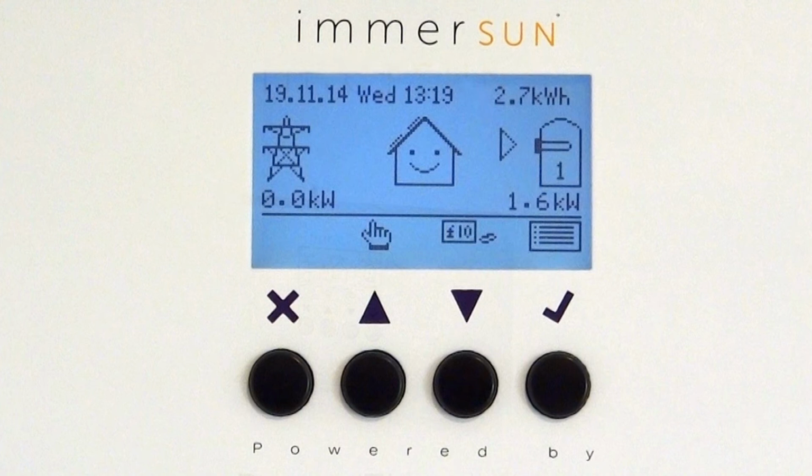The main screen shows the status of the ImmerSUN. Once the ImmerSUN is connected and operational, it should display the correct date and time. To the right, the Savings Today icon will alternate between kilowatt hours and financial savings in the set currency. The current heater displays the symbol for the heater being heated along with the heater number. Heater power shows the amount of power currently being sent to the heater. When the heater has reached its set temperature, the kilowatt value will display hot.